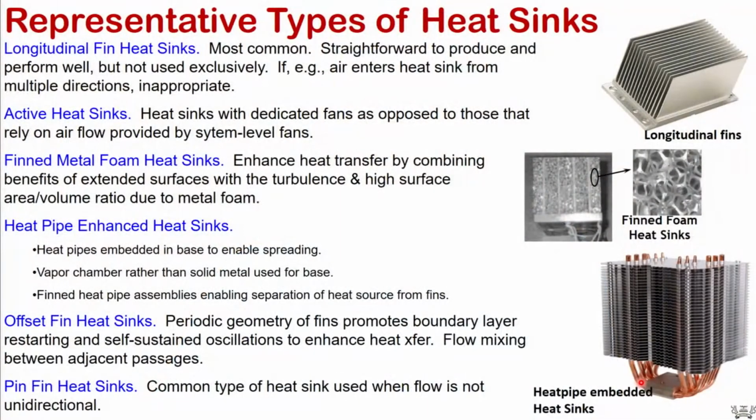And then there are heat pipes. Heat pipes are liquid vapor devices where the phase change from liquid to vapor carries heat from location A to B. It is a better thermal conductor, and heat pipes are typically used as a means to transport heat from location A to location B due to phase change phenomena. We won't get into the details of heat pipes, but these heat pipes are typically placed very close to the heat source.